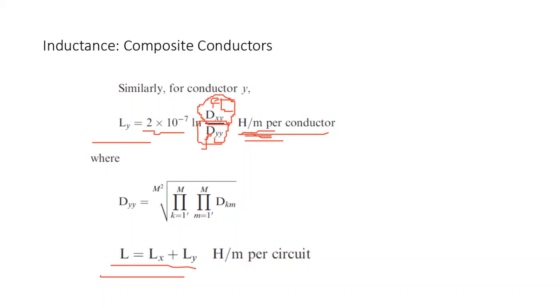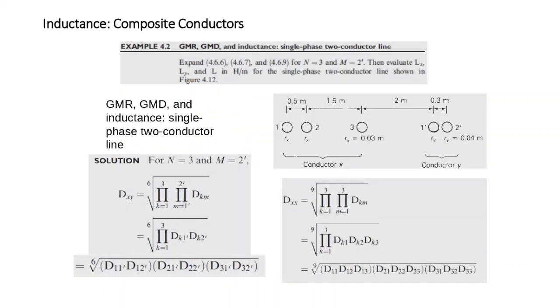Air conditioners of 3 ton, that's what you will see in the mosque, for example, this big one, and also some houses. Houses need 3 phase if they have more than 2.5 ton. 2.5 is single phase, 2 is single phase, 1.5 ton is single phase up to 2.5.